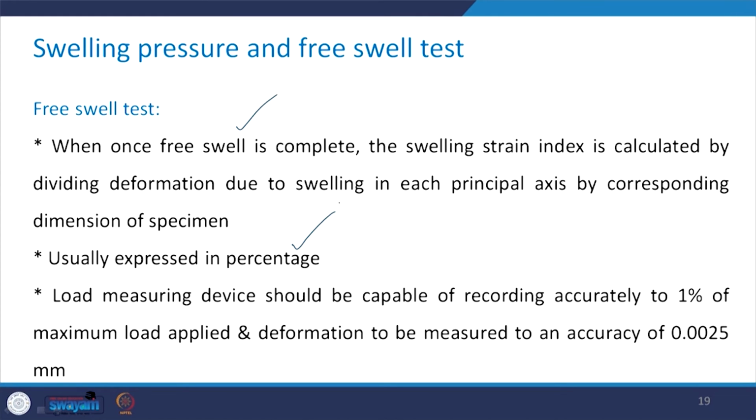One needs to be careful about the load measuring device. It should be capable of recording accurately to 1% of the maximum load applied, and deformation to be measured to an accuracy of 0.0025 millimeters. So, you have to be careful about this load measuring device.